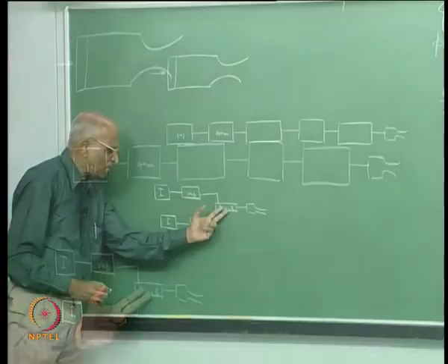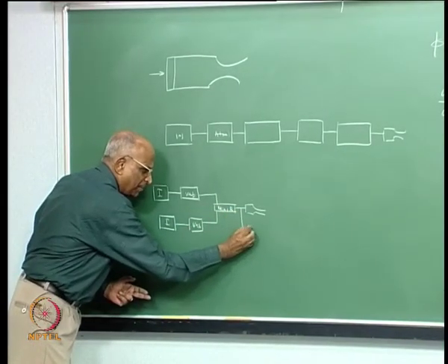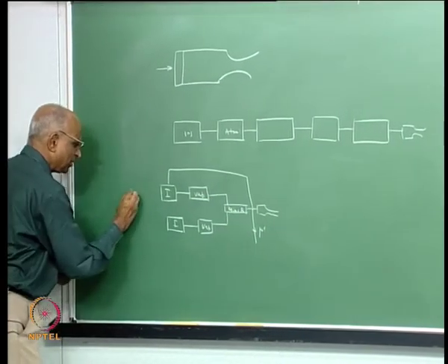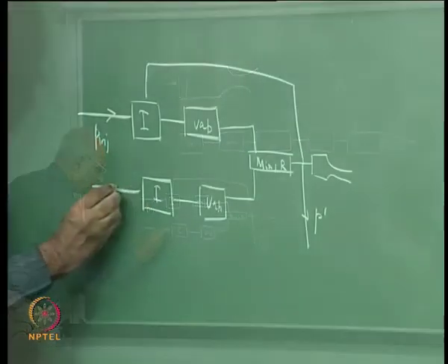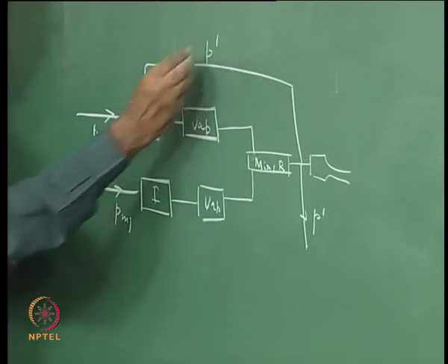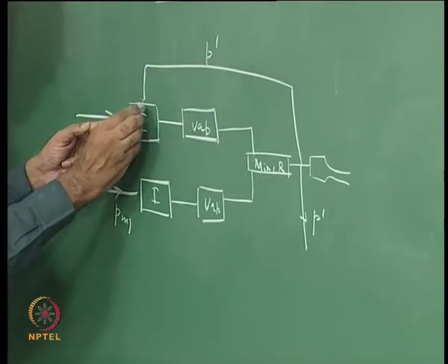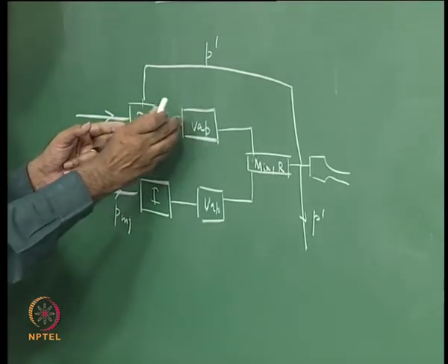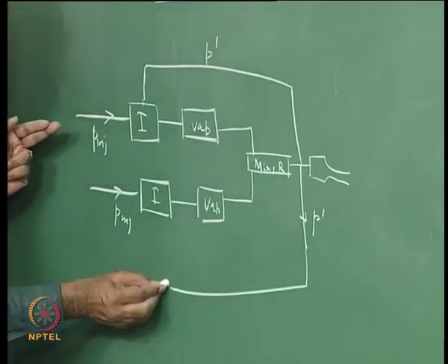and the mixed one is what gets injected out of the chamber. During this process of combustion, if there is some oscillation, namely P prime, it gets back into your injector over here. This is where you are injecting P injected. This P prime gets modulated in your injector, and therefore you are getting some change coming into your chamber again, your vaporization gets affected, and this becomes something like a feedback circuit.